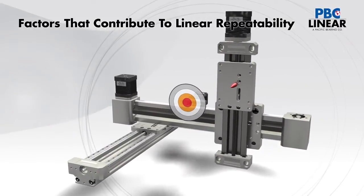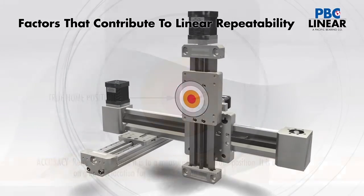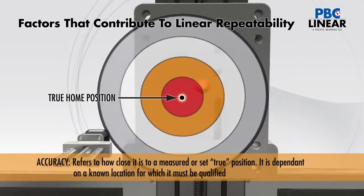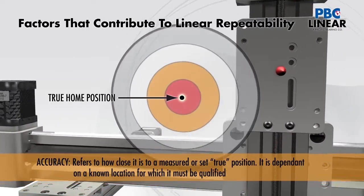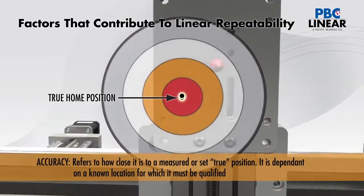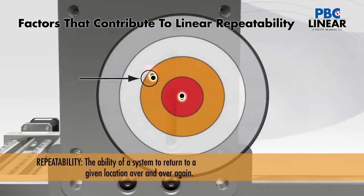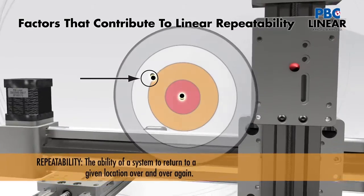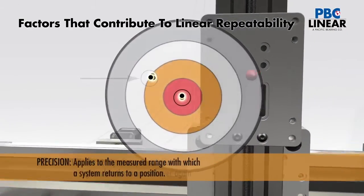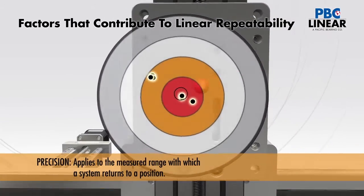First, let's review the differences between accuracy, precision, and repeatability. The accuracy of a linear slide refers to how close it is to a measurement or set true position. It is dependent on a known location for which it must be qualified or calibrated. Repeatability is a term that most often applies for linear motion. It refers to the ability of a system to return to a given location over and over again. Precision applies to the measured range with which a system returns to a position.